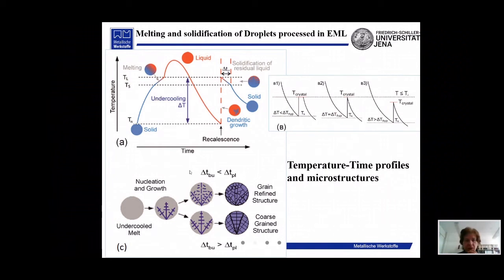And then we can calculate the time for unstable structure, building unstable. And if the time for instability is smaller than the time of staying at the plateau, then instability comes and we have refined structure. So this primary structure is destroyed into several parts, several units of this structure. And then we can see, as after complete solidification, we have refined microstructure.